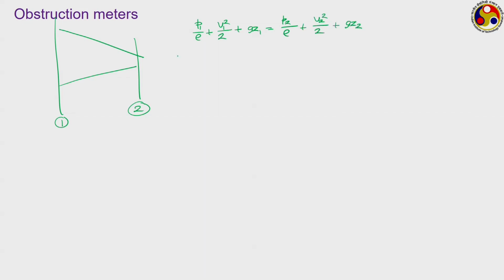And if there are any frictional losses, quite often we add HF, a loss of pressure head in a way, sometimes not truly pressure head, like a G HF term, where HF refers to a pressure loss head or some kind of loss coefficient, but here we are not going to talk about this for now at least.